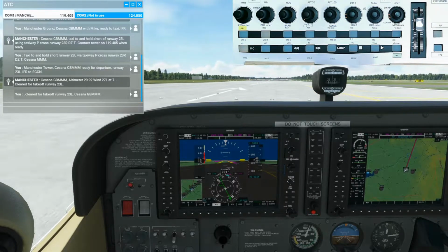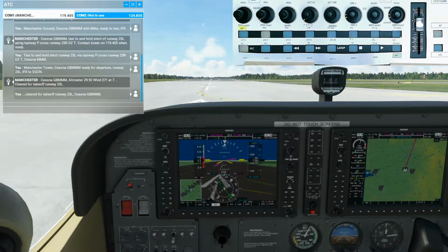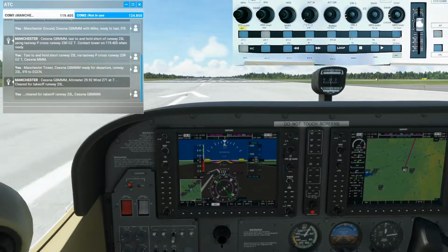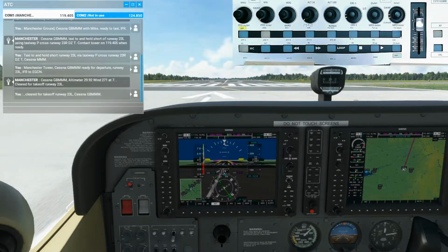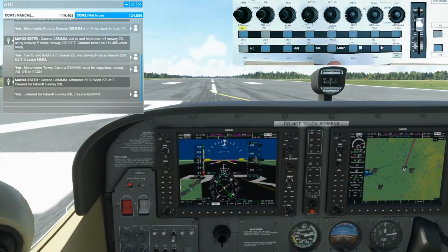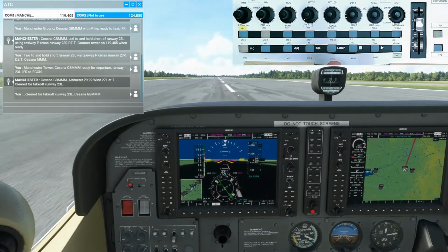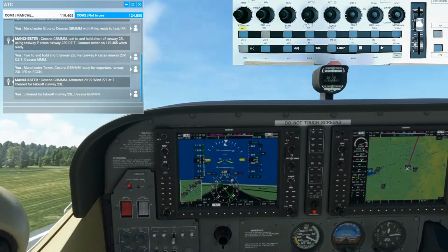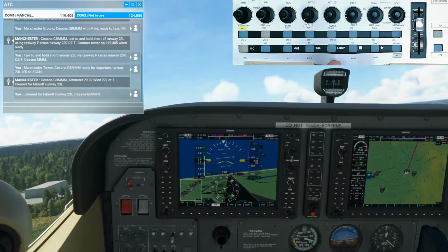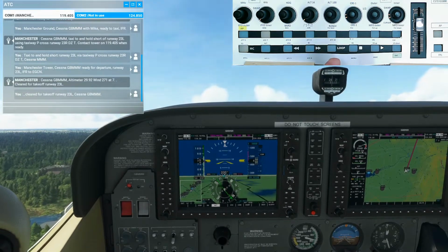If you watch the speed tape, you'll probably see when we get to 72 knots, the best climb speed marked. Okay, let's give it full power and away we go. Try manually flying the runway heading as best as possible until there's no usable runway left.